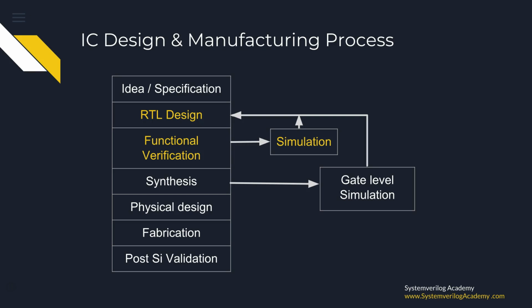In the functional verification phase, apart from checking the correctness of the RTL, the quality and completeness of the testing process will also be ensured by using coverage analysis techniques. The RTL design and functional verification phases are usually called the front-end phase of the IC design process.